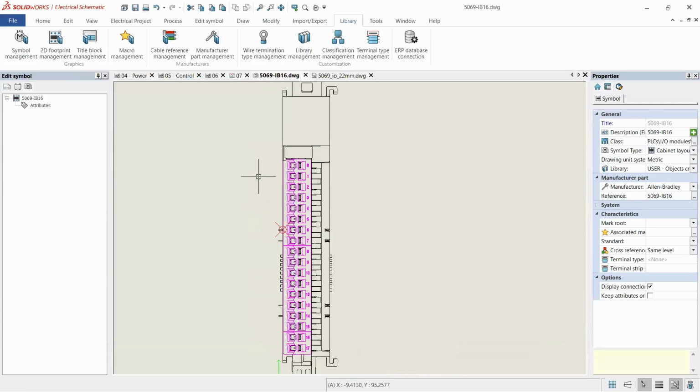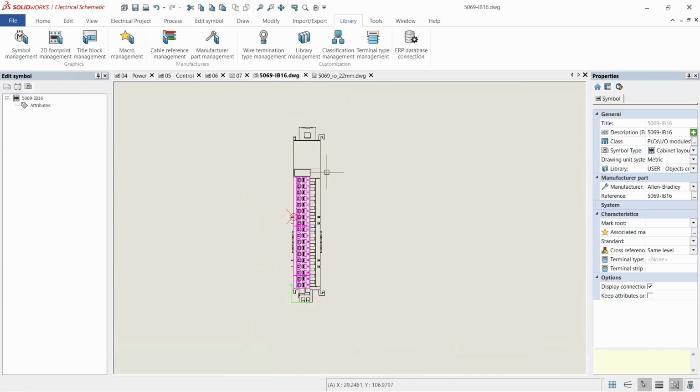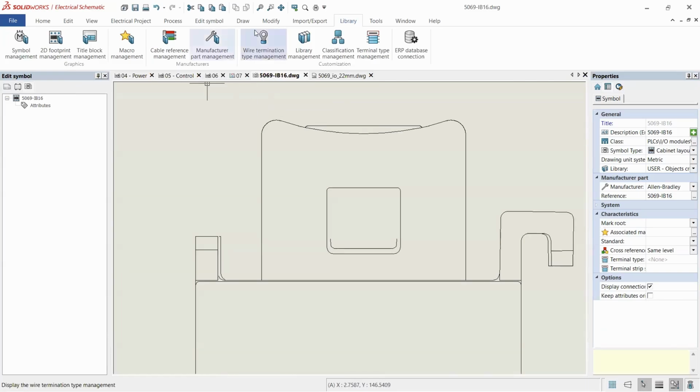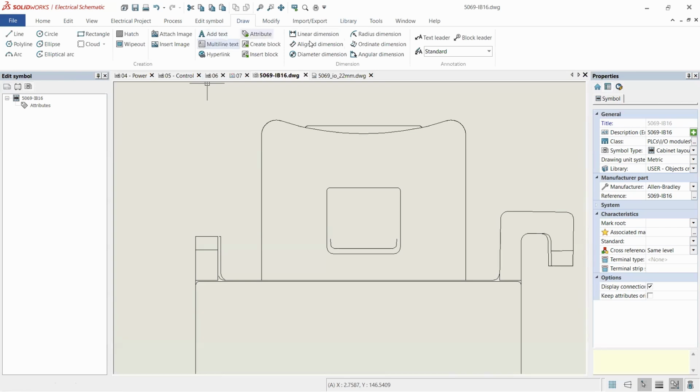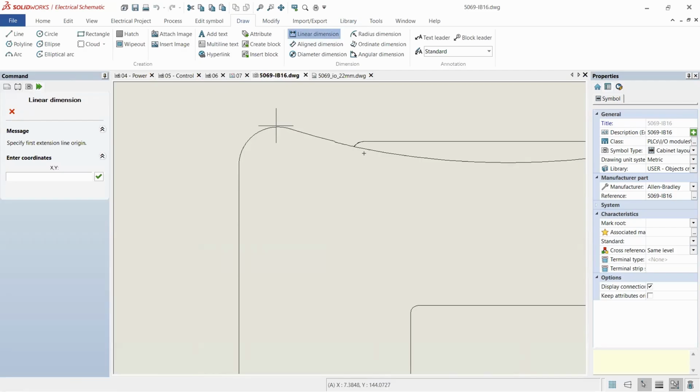The scaling happens automatically. This will be sized appropriately to our drawing, regardless of scale. We set the scale in the drawing and SolidWorks figures it out. It says this should be 57 millimeters wide and we'll scale it appropriately. So it's important to have those as accurate as we can anyway. I mean, super precise doesn't really matter. There's obviously a point of diminishing returns, but let's do a linear dimension. We need the height, and we need the big height. So again, I'm not going to be able to snap to the top of that curve, but this will be close enough.